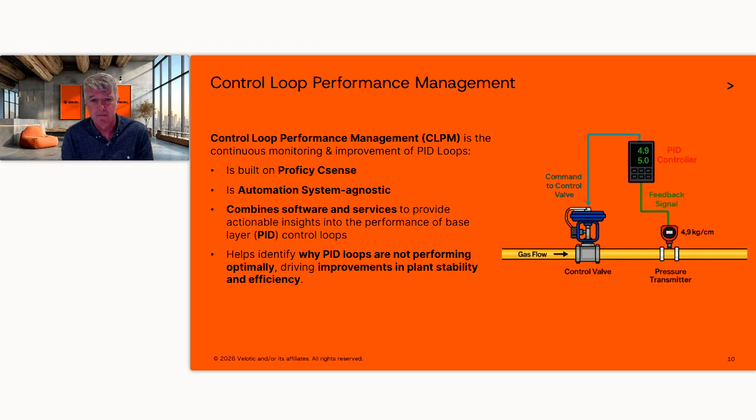If you think about this like a car with cruise control, right? As soon as I have my cruise control set at 65 miles an hour, if I go up a hill, I want it to push the accelerator. That's the manipulated variable. As soon as I start going downhill, maybe I want it to come off the accelerator so it can keep my speed. But because I'm going downhill, the car is now going faster, right? So you want to make that as smooth as possible.